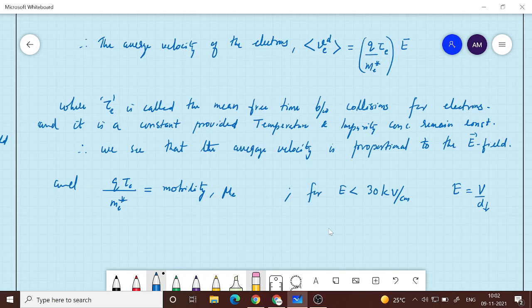We need to look internally at the reason for the creation of high field at 5 volt, or yesterday we saw 7.5 volt in the experiment. We had a breakdown. The reason is that D, across which the reverse bias potential is applied, is very, very small.